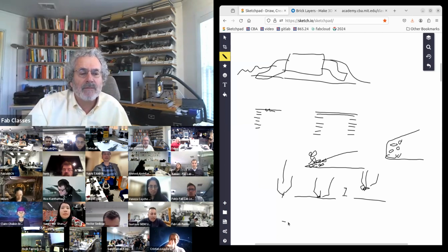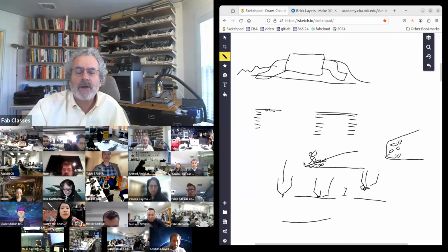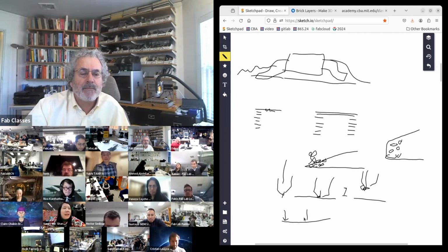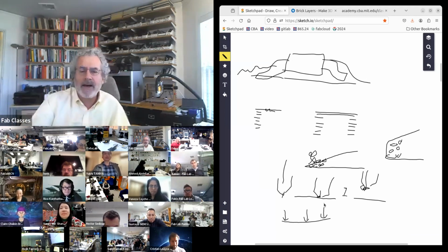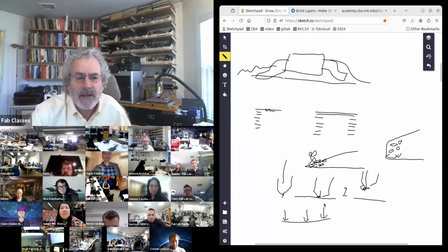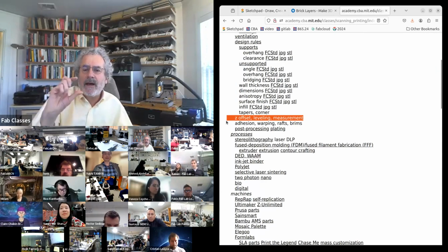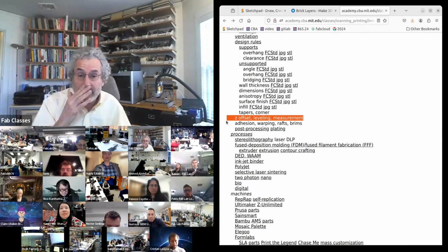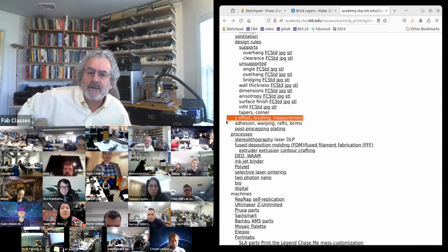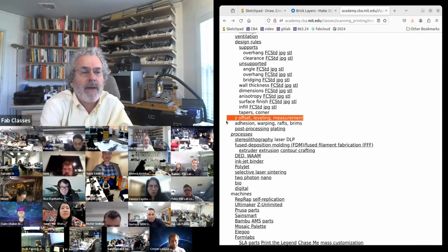Typically, the beds aren't perfectly flat. They can have a little curvature. So what good printers do is they dynamically probe the bed. They make a mathematical map of the height and adapt to it. If you don't do that, you'll get bad print quality. And even entry-level printers know how to do that now. So it's very important to have a printer that can map the bed.